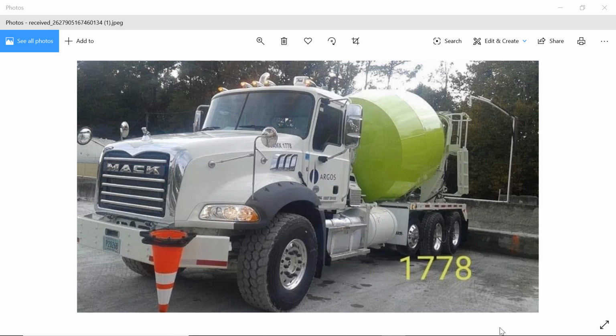Free moisture is equal to 6.53 minus 2.50, which is equal to 4.03%. Example 4. The total moisture content is determined to be 2.81% for a stockpile of fine aggregate. The same aggregate has an absorption of 1.4%. What is the free moisture? Free moisture is equal to 2.81 minus 1.40, which is equal to 1.41%.